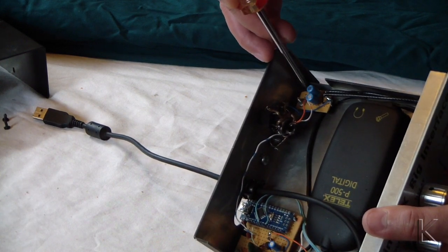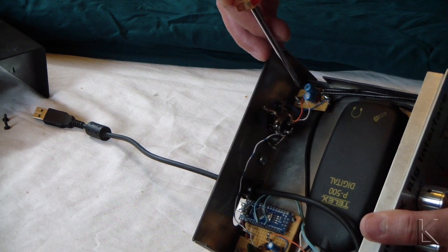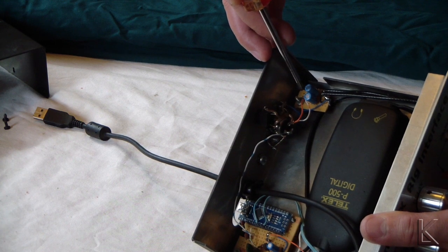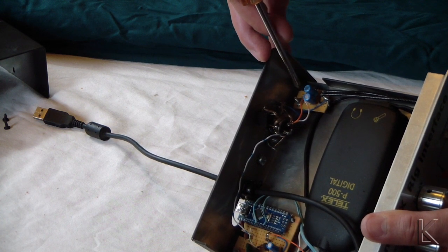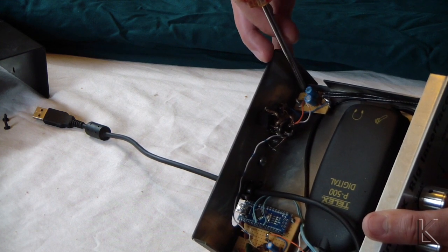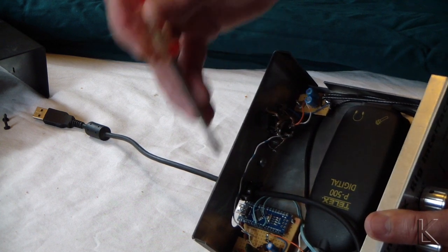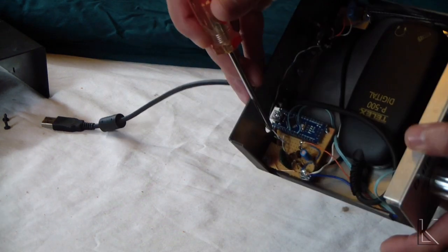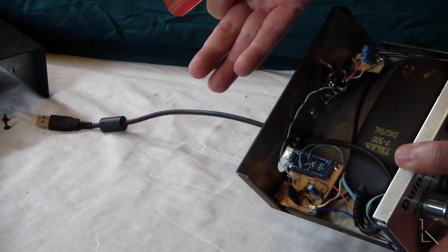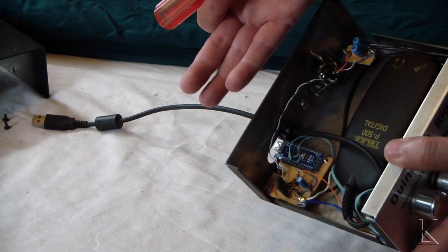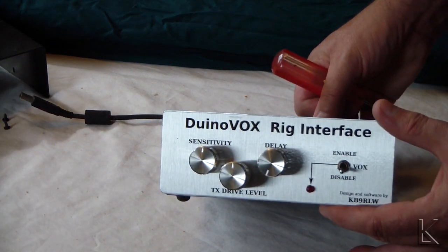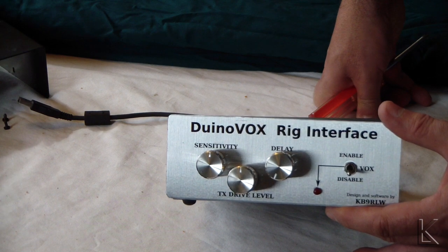If you want to isolate your radio from the electronics, instead of coupling capacitors, you could use a couple of 600 ohm isolation transformers. It was extra cost. I've never had a problem using capacitors, but for some older radios you might want to isolate using transformers. And the keying circuit, again, I used a simple transistor collector switch for the keying circuit, but you could use an opto isolator in place of that transistor and it would work exactly the same. So easy enough to change if you choose to. So that's the inside of it. Let's take it over, hook it up to the radio, and I'll give you a demo of it working.